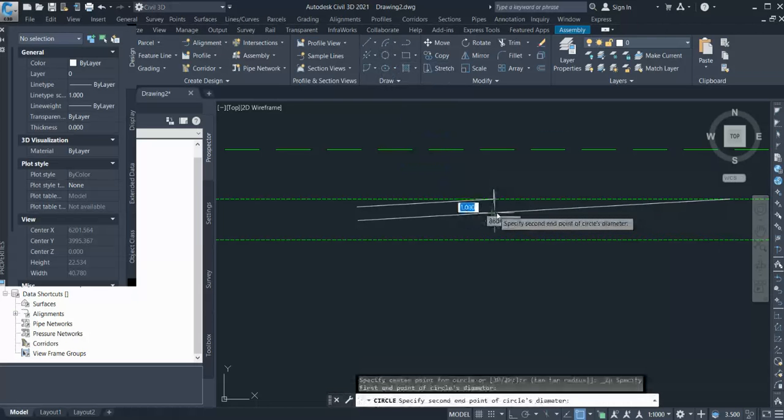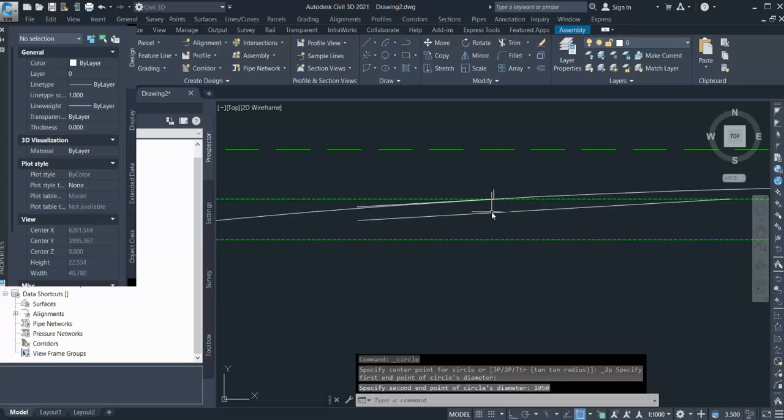Why am I going with a higher radius to begin with? Because I don't want any super elevation in my diverging area when I start to divert. You can provide super elevation on the actual loop, but you shouldn't need to provide any super elevation where you are actually diverting unless you have any side constraint. So I start with the higher radius. I'm going with 1050.